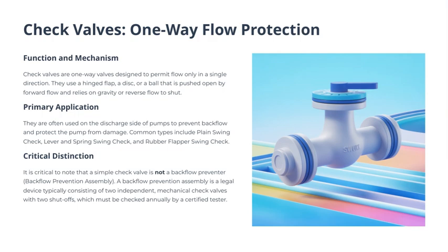And, to ensure it's functioning properly, it must be checked annually by a certified tester. Now, these assemblies are often installed on the discharge side of pumps. Their main role is to prevent backflow, which can cause serious damage to the pump itself.